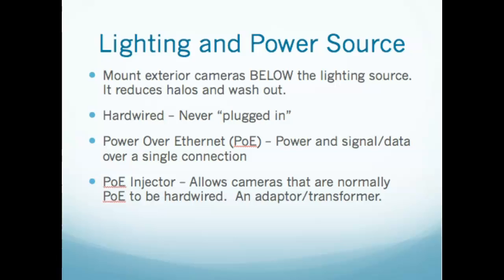Your camera should always be hardwired whenever possible. They make kits that you can essentially just plug the camera into a standard outlet. And I have seen cameras where someone has purposely installed an outlet close to the ceiling, mounted a camera on the ceiling, and run the cord down and plugged it into the wall. Or put a plug right behind where you mounted the camera on the wall. Bad guys are pretty stupid, but they're usually smart enough to unplug the camera before they take it with them. You should hardwire your cameras in so that wiring's not exposed.